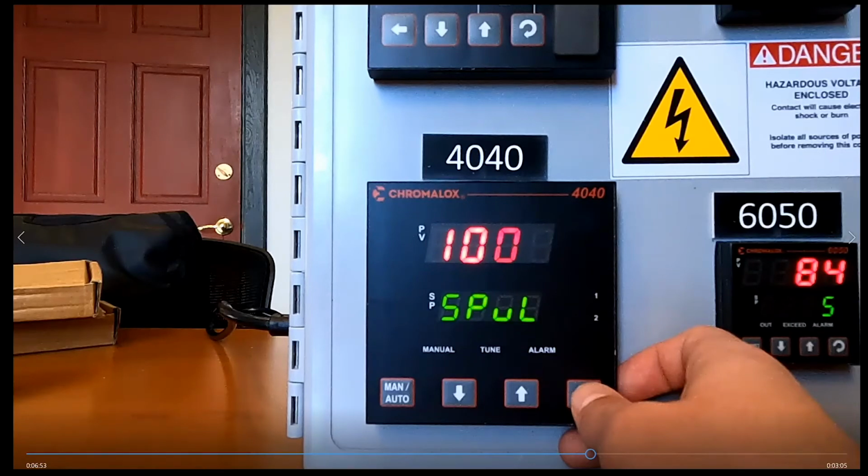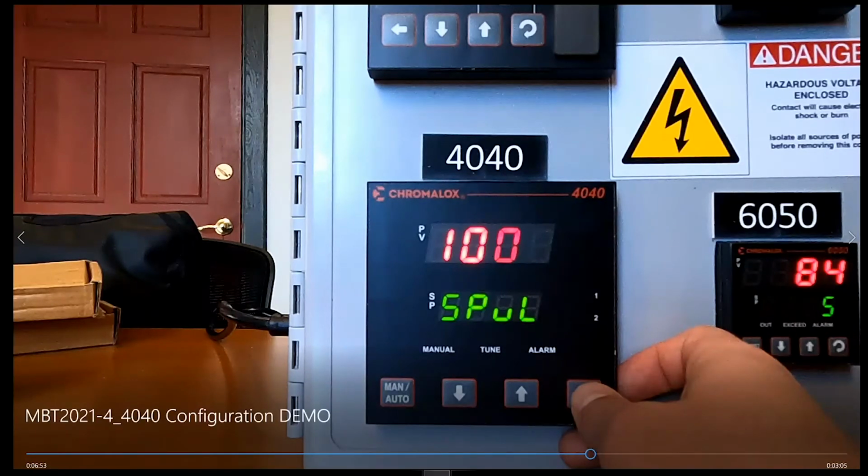So, let's say you're trying to control a process around 100 degrees Fahrenheit, and your operator is really concerned, maybe there are some new people on site. You can narrow down the absolute maximum and minimum set points to be right around 100, so that even if somebody new is using this controller, maybe unsupervised, they can't really mess it up too bad. That's what these are used for, just to make sure that they can't set some outrageous value for their set point.